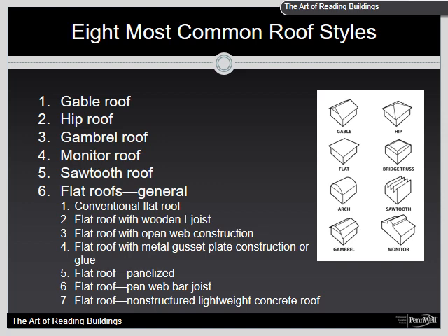The lightweight gable roof construction is different from our coarse or traditional, and that is because it uses traditionally metal gusset plate connectors, which may vary in size and thickness and depth of penetration. However, 18 gauge steel plate with prongs at 3/8 inch are most common.